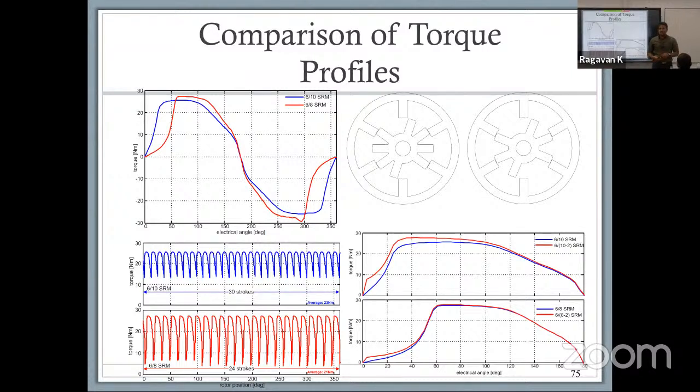It's the same as transmission line, right? There's a reason, if you have done your fundamentals of power back in the day, we start talking about why we supply power using 3 lines, why it is not single phase, right? And why do we not have a 5-phase, or 7-phase, 9-phase? Because the value that you get by bundling 3 conductors, 3 phases, it diminishes. It's a law of diminishing returns. You don't get the same improvement for the cost that you are going to pay for it.